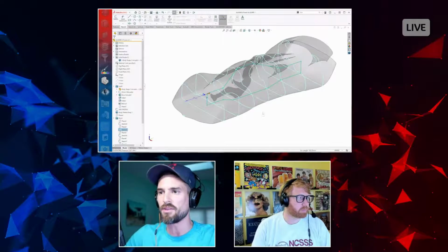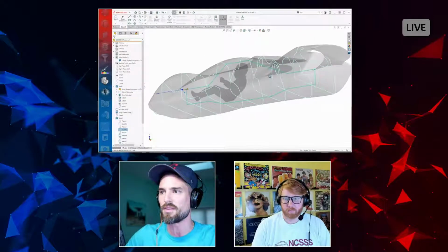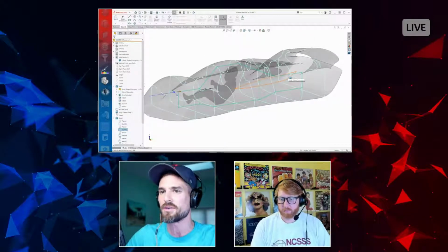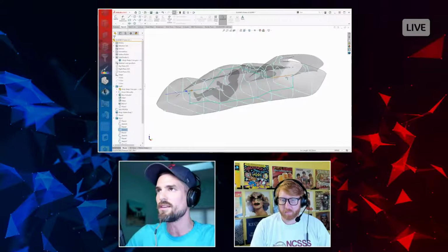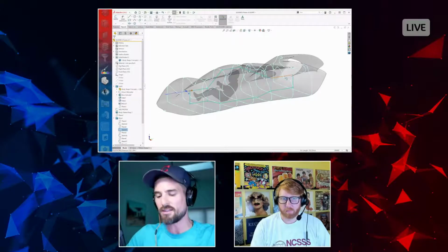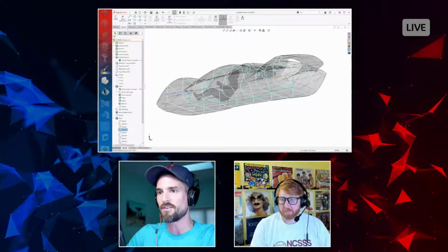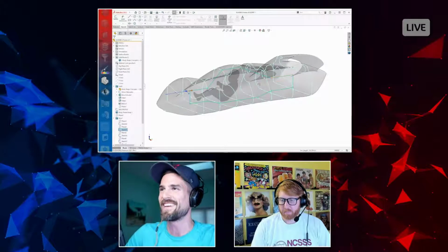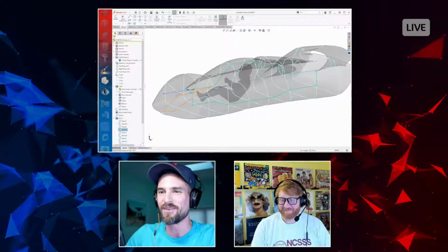And by the way, if you're looking for a recommendation for keyboard shortcuts, what I do for most of my favorite keyboard shortcuts is just do Alt key, whatever letter the tool begins with, because that's readily available. And my thumb just naturally kind of sits on the Alt key. So it's really easy. So Alt T for tangent edges and Alt G to make them gone. And they're right next to each other. So it works out well.